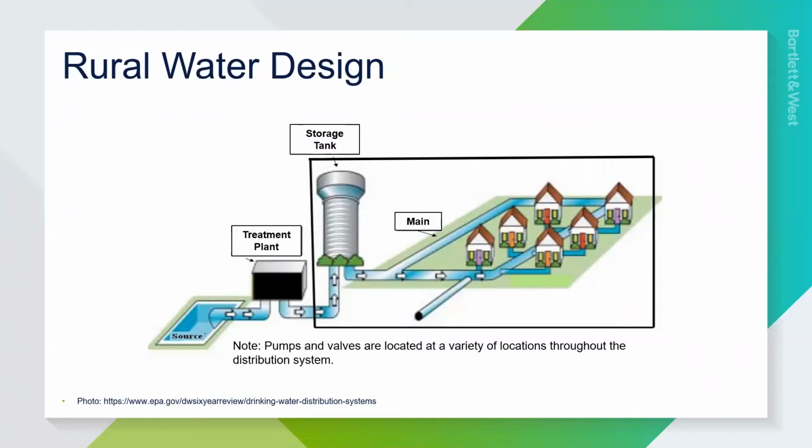And so to illustrate this, looking at the slide there, this is just a simple graph showing the components of a rural water system, i.e. an intake, treatment plant, a storage reservoir, and residences connected on a distribution system. And with this, one of the most critical, if not the most critical design elements of a system design is something called the instantaneous peak demand, which is the short-term peak flow required by the customers.